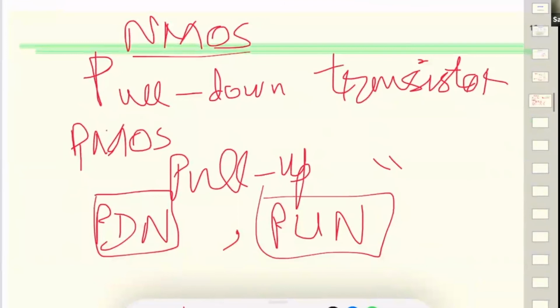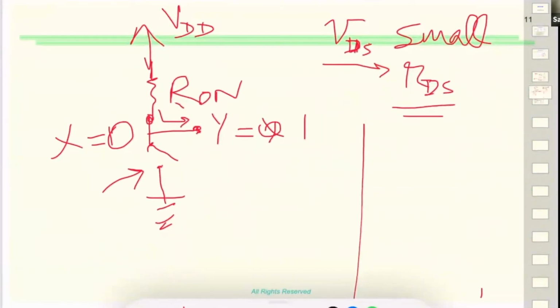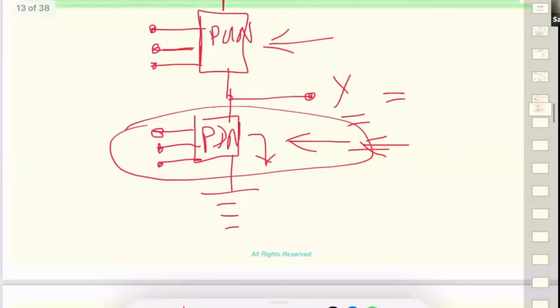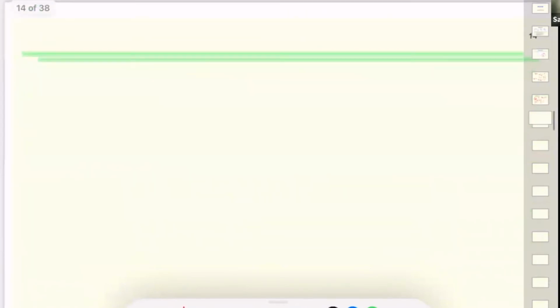And if we know where the pull-up or pull-down comes from, the high gate voltage would make an Nmos conduct, right? A low input on Pmos will make it open circuit. You have to just remember it, grind it down, because that's what gets into this idea of how it translates into an AND or an OR.